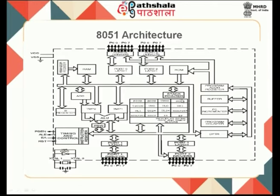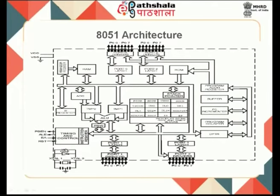Other than that we will have 4 ports, P0, P1, P2, P3. So, 4 ports are available. All these 4 have an 8 bit communication line. So, parallel ports are available, and we will have an oscillator. This oscillator provides the clock for this particular CPU, which in turn is synchronized with the machine cycle. So, the machine cycle is synchronized with the system clock, which is given by this oscillator.